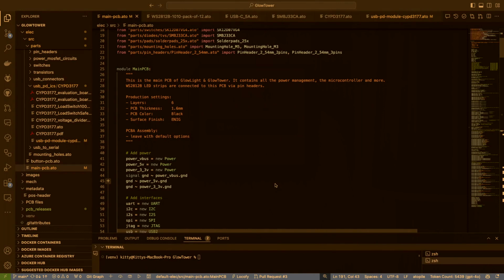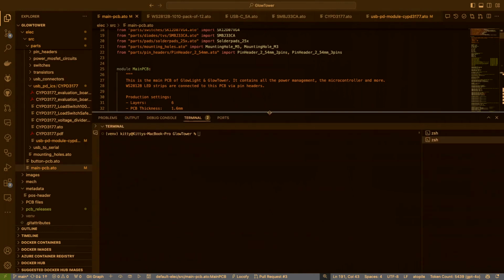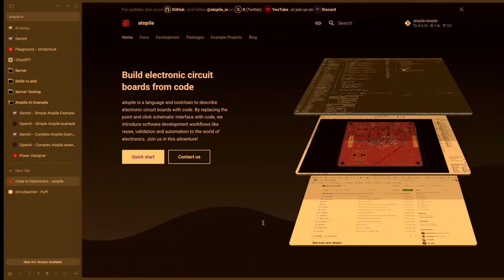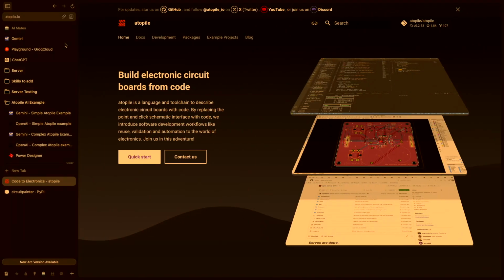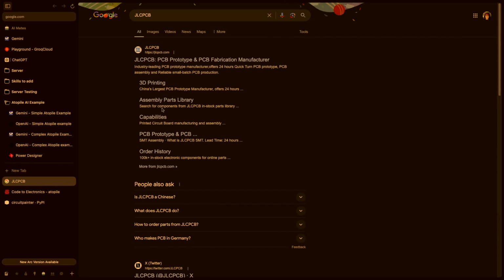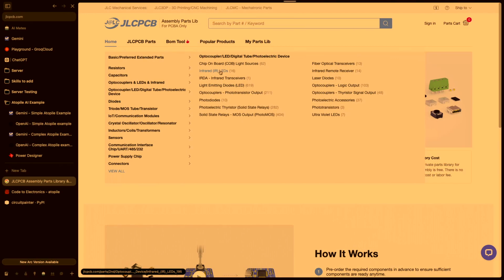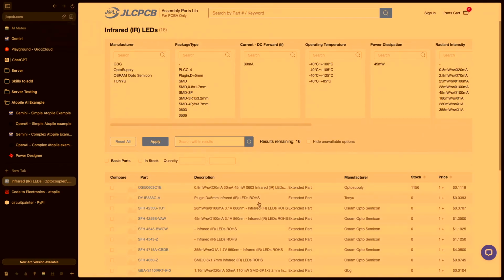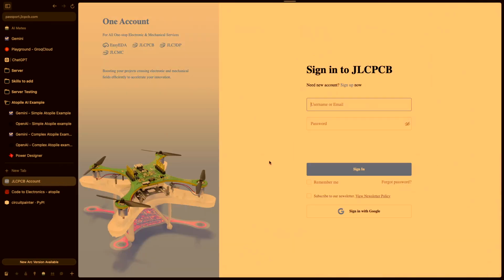That reminds me, I skipped over an important part here. Two things. For one, the approach I've been using the most, because I've been working with LCSC and JLCPCB, is that you have this components database from JLCPCB, and all these parts have their own ID, and you could decide to simply import them.